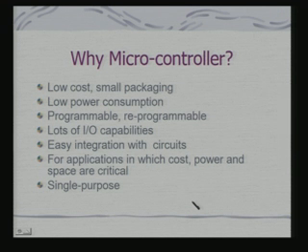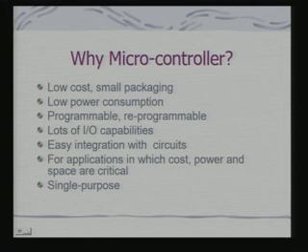Now, we have found that microprocessors are used for general purpose computing, and we are saying that microcontrollers are being used in many cases for special purpose embedded computing. The question is, why microcontrollers? Obviously, the dominating factor in this case is the low cost and the small footprint that it offers. Since embedded systems are supposed to perform specific tasks, we do not need the facilities of general purpose computing on a microcontroller targeted for embedded systems. So, we can have multiple peripherals integrated together onto a single piece of silicon to get a chip which has a smaller footprint as well as less power consumption.